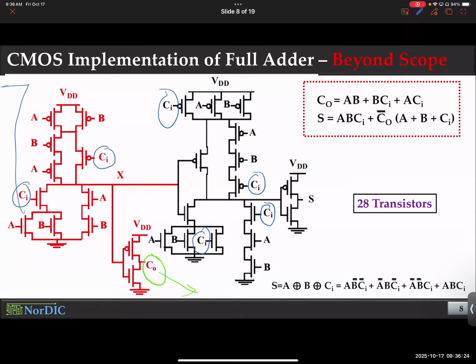It is bad enough to drive one capacitor. Just think about driving 6. So it takes a while for the carry in to charge the capacitors enough for the circuit to eventually make a decision. So it's a slower process. Do you appreciate it now or no?